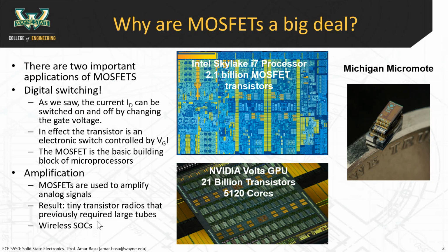The signals coming from there might be like negative 80 dBm, even more, like negative 100 dBm or so. So you need fast amplifiers, and you need sensitive amplifiers to amplify that signal from the cell phone tower into something that your cell phone can read, right? And so the fundamental component of a wireless radio is an antenna and an amplifier.